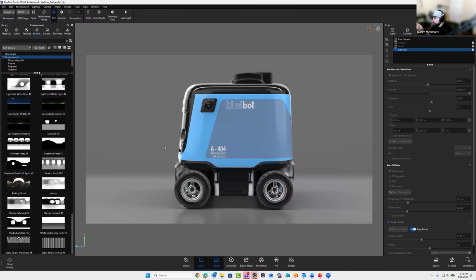If you're working with those materials, increasing the sample count for that material will greatly help you deal with caustics and light passing through. So there's ways to go around it if your scale isn't proper. But again, like working from CAD, the best and most sanitary option is to try to keep all your scale correct. And that way you have realistic effects. But the biggest thing is just make sure those sample counts are a little bit higher. It will help with caustics and light passing through, and play with the transparency distance a bit so that you can achieve the look that you're going for.